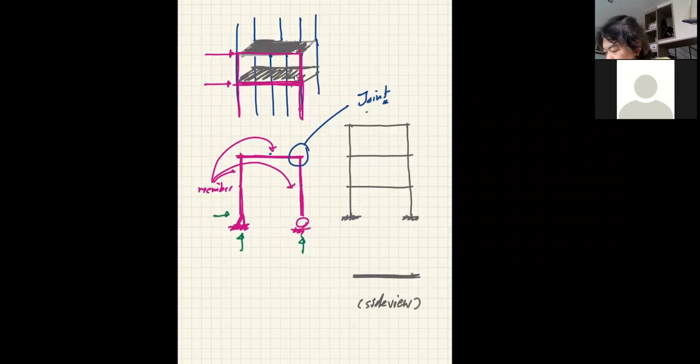Side view of the floor. When the load comes to the side, what's going to happen to this? It's just going to blow by, correct? So you need something of a system to help put everything together to form a structure. With the floor system alone, there is nothing to help resist the horizontal load. You need to have something vertical.